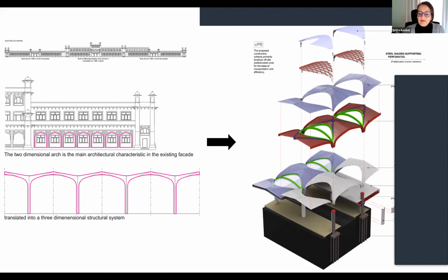This is the structural system with, of course, because we cannot shut down a running station, the columns, of course, have an in situ foundation, but then the columns will be prefabricated, the truss systems, the slabs will be prefabricated, structural roof system will be prefabricated and built up as soon as possible with a running station in the background.